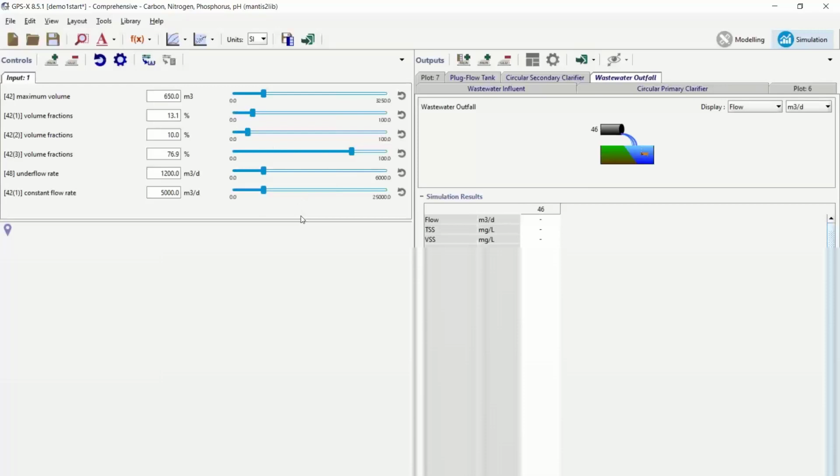We're not doing dynamics, so I'm actually going to remove that one. And also, while we're here, I'm going to throw the mixed liquor. So coming out of this tank, go to the concentrations menu, grab the mixed liquor, and put that on there as well. Okay, so now we have this, and if I run steady state, there's my 15 days. That was something we set it for. Mixed liquor is 32.66, so that seems reasonable.